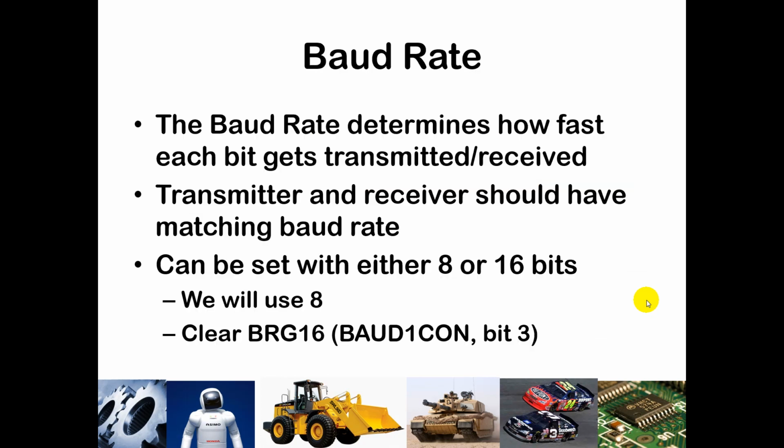So let's talk about breaking down into the various control registers and what will need to be set up and how those registers work in a little bit more detail. So baud rate can be controlled in a variety of ways. There's multiple formulas that can be used depending upon how you want to configure it. You can either use an 8 or a 16-bit control on the baud.